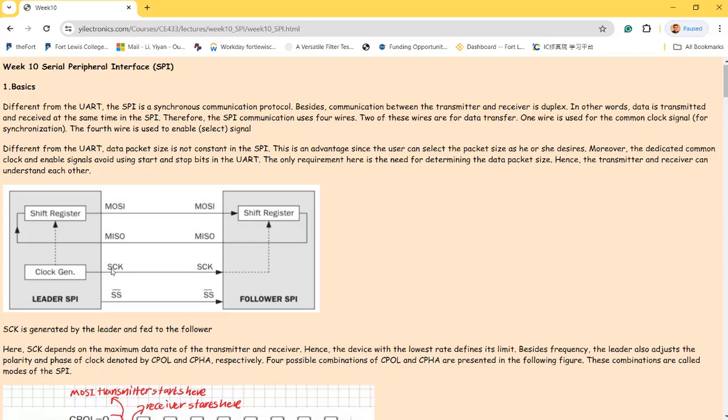And it has one clock and just one wire. So that clock is going to synchronize all the operation. That's why it's a synchronized, or synchronous, communication protocol. However, UART is not synchronous, and I2C is not because it's just one wire. So compared to UART and I2C, this is one of the questions on that.